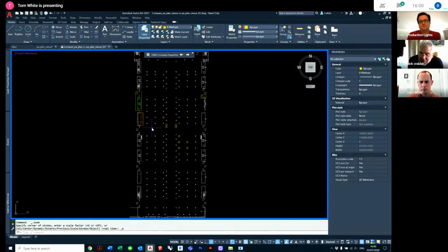For those of us who receive plans that are updated on a kind of weekly, fortnightly basis, to be able to run the compare function, see the stuff that's changed, is enormously helpful, as Tom said. And when you first showed me this, I got hugely excited. And for those who aren't real CAD people, Autodesk have a program called Design Review, which has the compare function in it. And as Tom said, so long as those two drawings have the same base point, it will do it. And that's a free program. It's as easy as you like, and it sits there as one button and just shows you those green and red changes. Absolutely free. Yep.